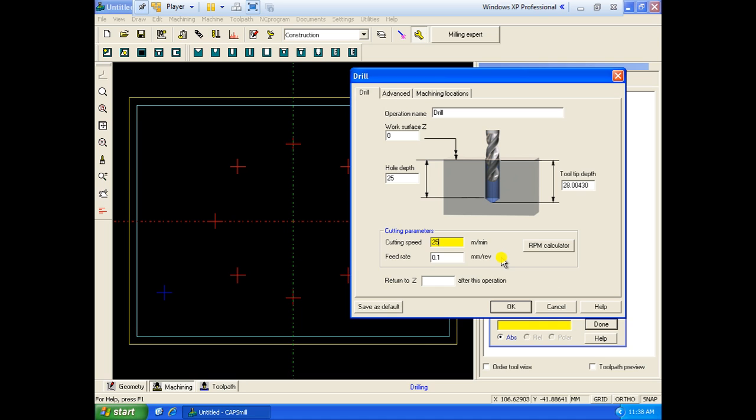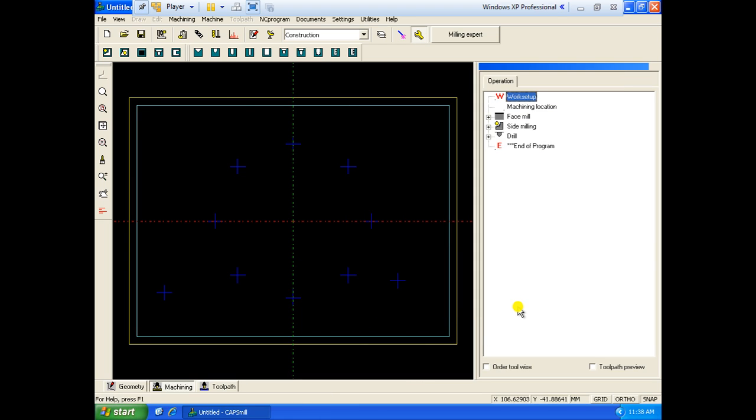Okay, give up. So drilling is completed, and the remaining 2 holes were there, right? Here we need to make a metric 8. What do we mean by metric 8? That is a metric thread, an internal thread we need to provide. Here the metric thread is 8 mm, that is M8, right? M8 means a metric thread of 8.